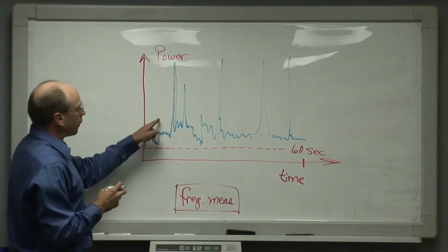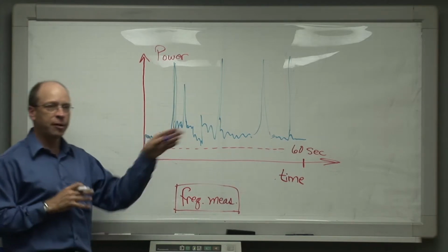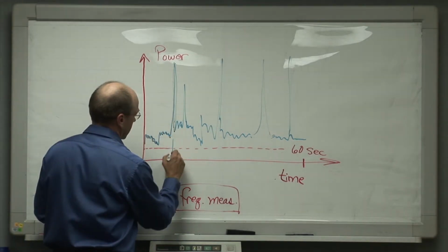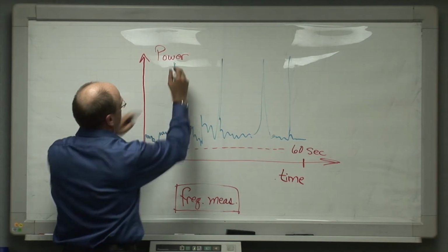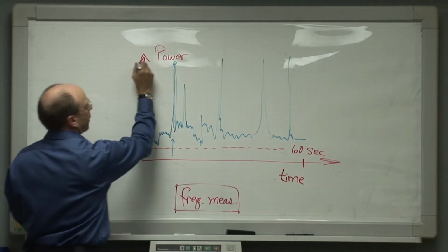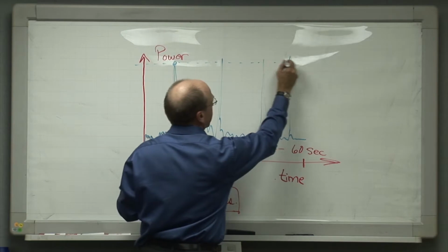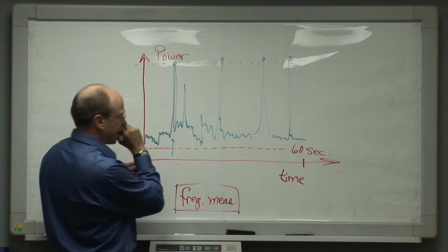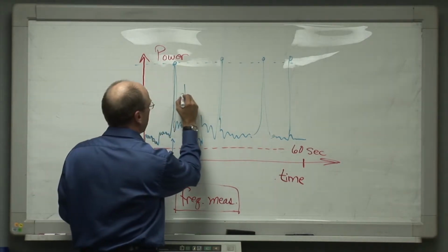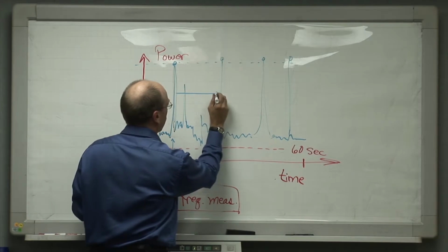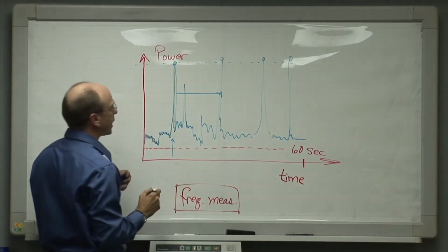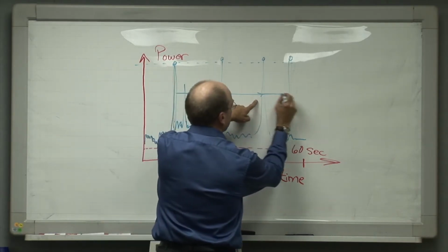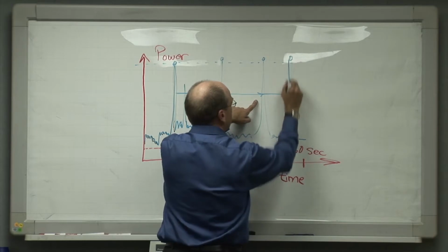So what's going on here? Well, the radar has some complex operation where it may be tracking targets, doing some kind of a search interleaved with that. It appears, when you look at this, that from any given moment when the radar does apparently look in our direction, because we know that this thing seems to hit this maximum level every so often, we can look at this and say, okay, well, the radar waited that long before it looked over in our direction again, and then it looked in our direction again in a little shorter interval, and then again in an even shorter interval after that.